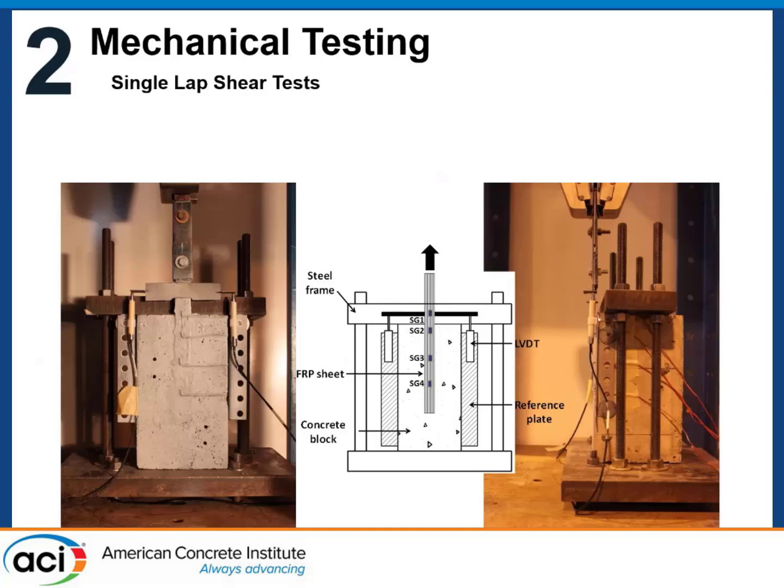What I have here is a photograph of the single lap shear test after all these different variables. You take the specimen now and you test it to failure. And I think Christian would probably enjoy looking at all the details of the testing. And yes, we took pictures in several directions and used DIC as well, to capture whether we were having out-of-plane deformations, and strain gauges to measure the bond slip and bond performance and derive information from that.